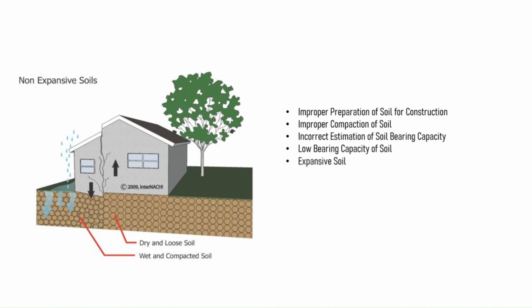5. Expansive soil. Expansive soils are those soils that expand and shrink considerably as seasons alternate between wet and dry. If a foundation has expansive soil below it and it does not expand or shrink uniformly, the movement in the foundation does not become uniform. This will cause stress on the foundation, which could lead to structural damage. 6. Construction activities nearby. Excessive vibration or excavation activities performed near an existing foundation would result in the underlying soil becoming loose support. Finally, natural calamities.